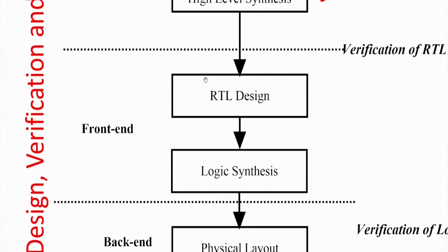It can be generated automatically, because we know that by solving Karnaugh maps and the Quine-McCluskey method, how an adder can be implemented, how a counter can be implemented. So all these basic block diagrams can be easily synthesized. So basically, this part we call the front end, which will take your block diagrams, make a register transfer level design, and from that make the gate level implementation.